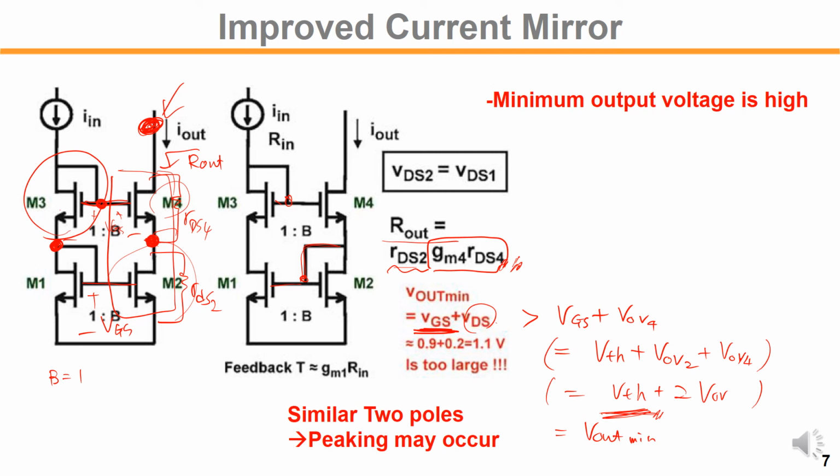So how can we avoid that? There's another way. By stacking this kind of VGS step, one VGS here, another VGS here, we have a 2 VGS stack. On the right hand side is also the same. The 2 VGS stack provides us a very small minimum V output at the current source output.